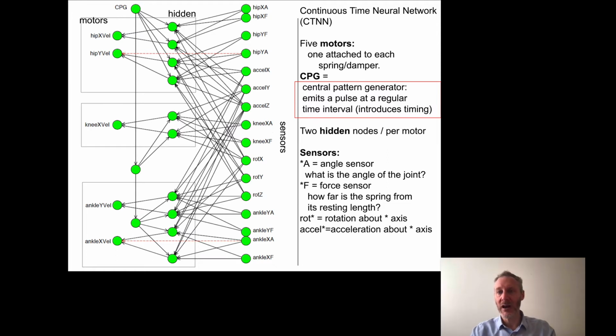There is also a velocity control, which is that the motor interprets the incoming value as a desired velocity. So if the value is 0.3 arriving at a motor, that value means the motor should achieve 0.3 radians per second. Or it could be revolutions per second, RPM. Doesn't really matter. It's something per unit time step. In this particular case, they're using velocity control.